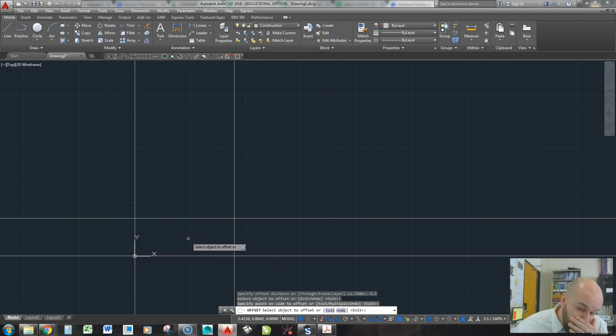Okay, so if I want to, I could go through and create that front view right now. Or I could go up and create the view from my top view, or my side views, or my bottom views, or my left side view, depending on what I think the best views are. For the interest of this exercise, what I've asked the students to do is to create the views they think are necessary to completely define this object.